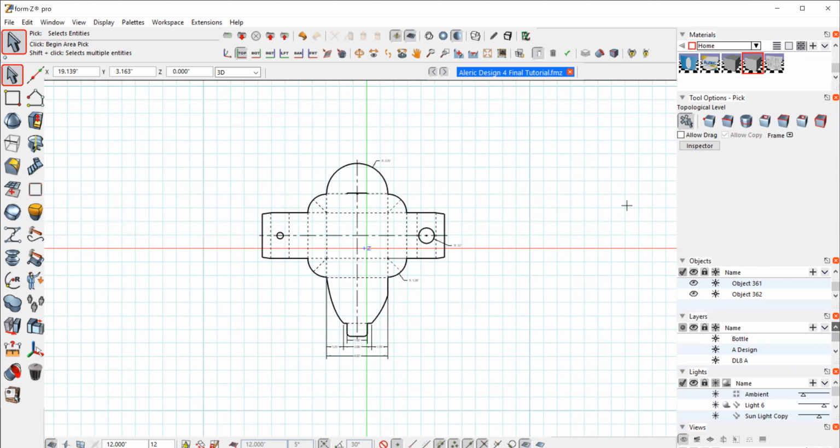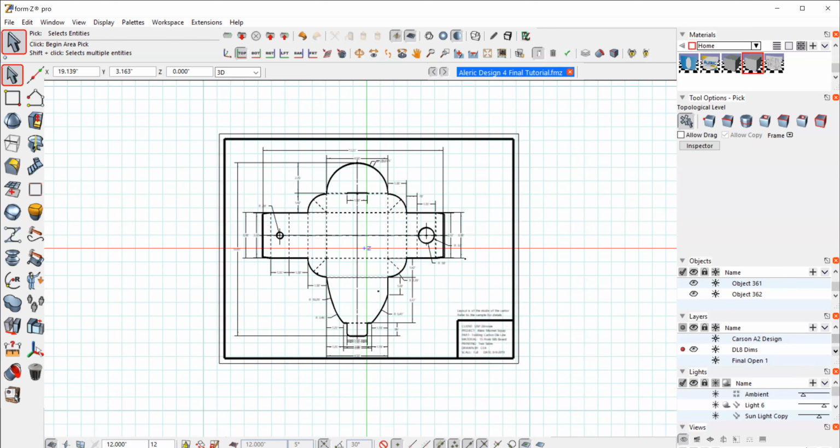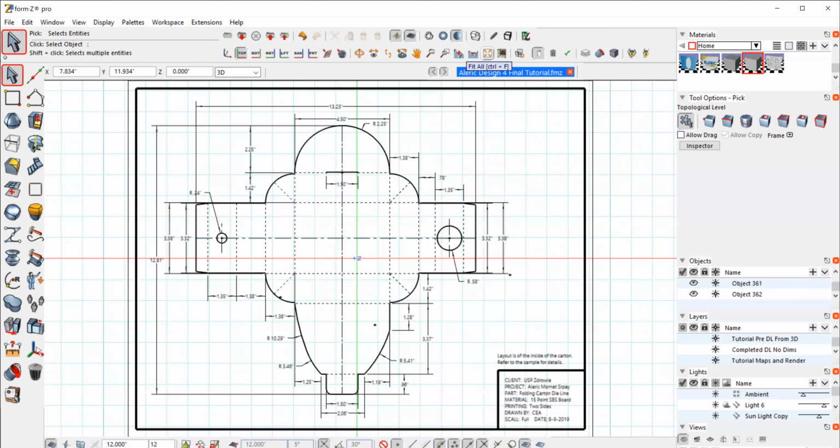So when it's done, let me show you how this is completed. And we put a border. And here we go. So let's just bring that in. So here I have all the line qualities and the dimensions. See here I have a dimension inside of the object. It's not the end of the world, but it's not common practice. If I had more space or if I wanted to, I could have pulled that straight up in here. I could have moved this over a little bit, but it's fine.